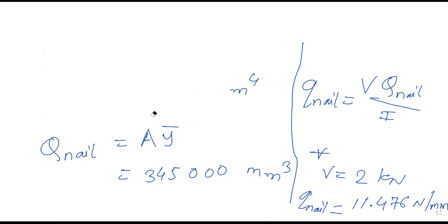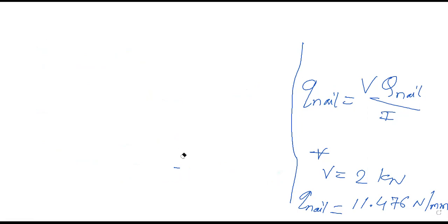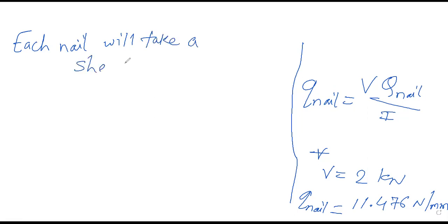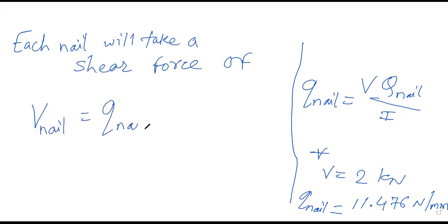Okay, so for that, after the Q nail, write down each nail will take a shear force of V nail is equal to Q nail multiplied by spacing. Yes, that we will find out.